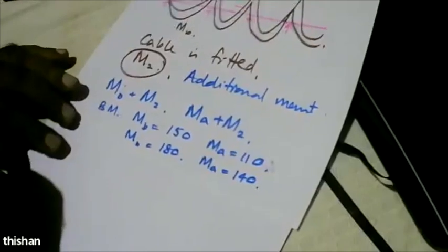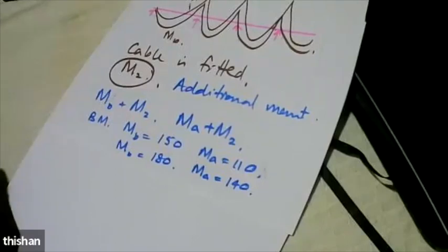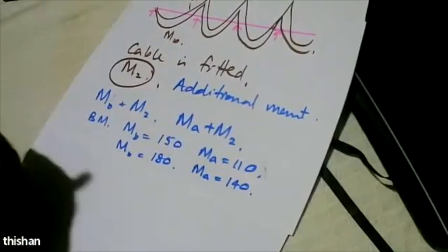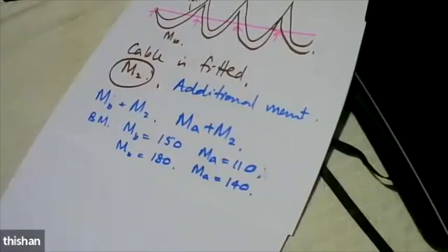So this was the problem faced by engineers who tried to design prestressed concrete continuous bridges. Because of all these difficulties, many engineers thought, okay, why do we want to make it continuous? Can't we make bridges by using simply supported spans? This prestressed concrete continuous bridge is the real pain, because you can't do the calculation. Every time you do the calculation, you find that the calculations are not valid because the bending moment has changed.